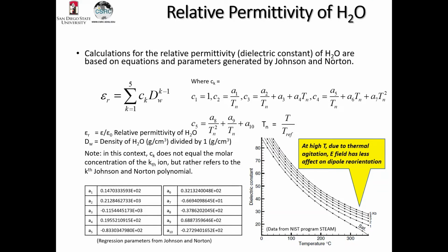Because at high temperature there's a lot of agitation of the water molecules, and they're not as amenable to reorient in the dipole. So it's low permittivity at high temperature because you can't store energy through reorientation of dipoles. In other words, its capacitance is less. Its ability to store energy through dipole reorientation is reduced because at high temperature you have a lot of agitation.